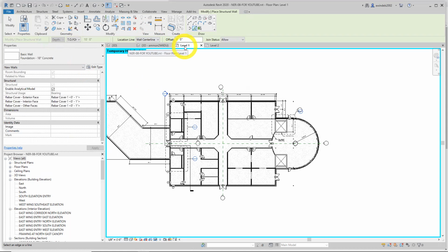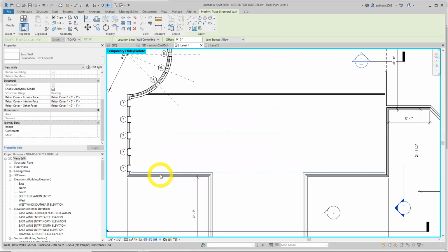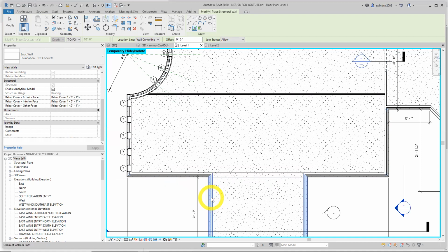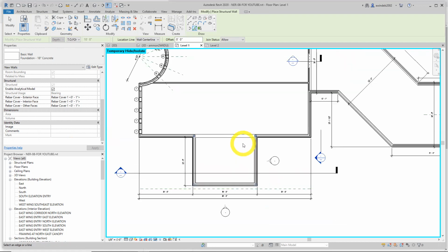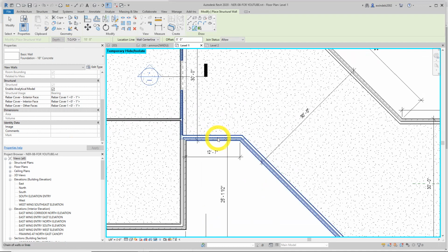This is a little bit of a tricky part, and I'll see if I can get through it as well as I did the first time. We're going to pick the center line of all exterior walls. So everything on similar to 8.52, corridor, both wings, everything. So we do this slow. Let me hover in here first and make sure I'm on the center. Start with this one. I hit the tab button. Accepted those. Hit the tab button, accepted these three. It's going to make a wall in here, and that's fine in this case. Hover in here, make sure I get the center right there. Tab.